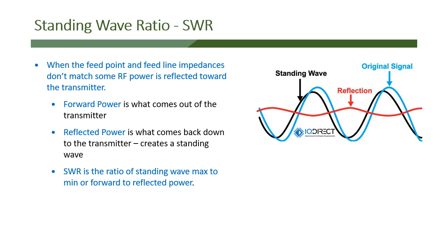100 watts. If you're down into the 5-watt range, you want to be a little bit tighter with the SWR because the losses can be more significant. If you have a 5-watt transmitter and you lose a watt, that is 1/5 of your power gone, versus losing 1 watt at 100 watts, which is only 10% of your power. So just keep in mind that when you have lower power, these losses can be more significant.